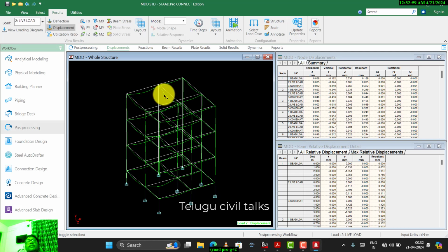When we add secondary beams, we can release the moments at the end positions. And cracked sections, as per code, cracked section values also we added, and the slab values also.